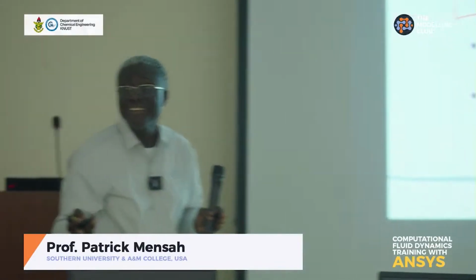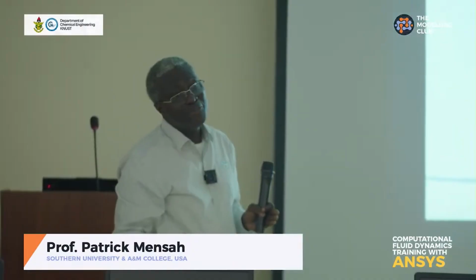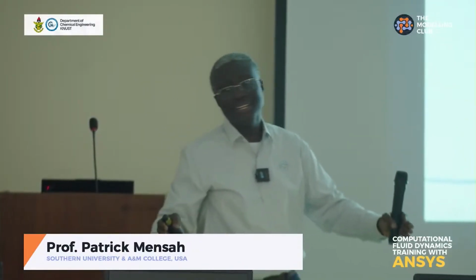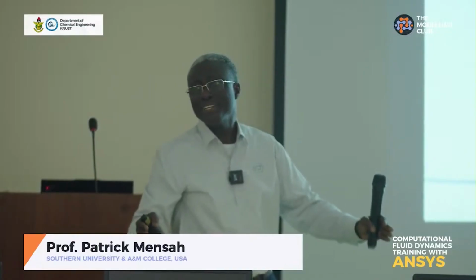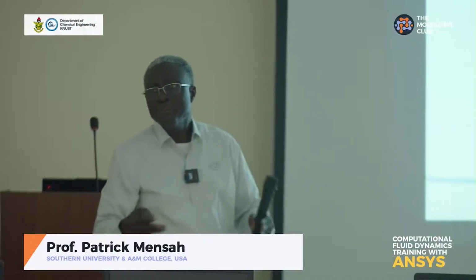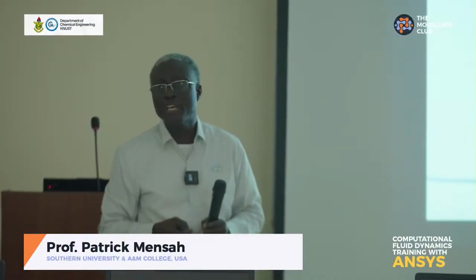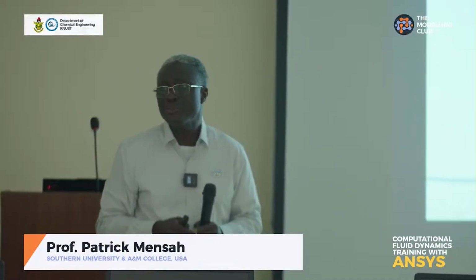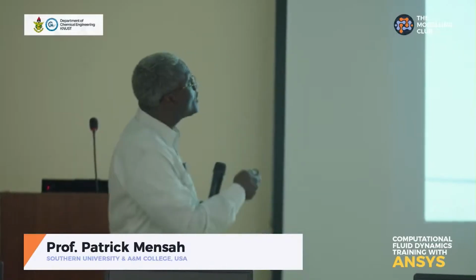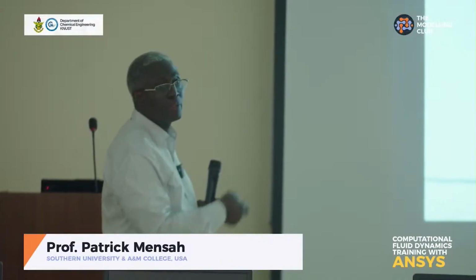That is 3600, right? Versus 5 minutes, then you're using a larger delta t, so it solves a shorter time, but then there will be differences in terms of the accuracy of the solution, and it's conditionally stable. Okay, that is what we mean by this.